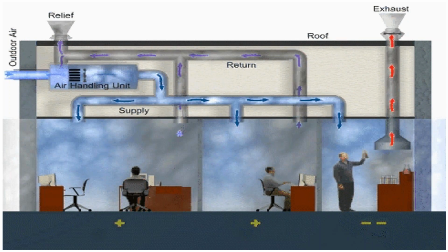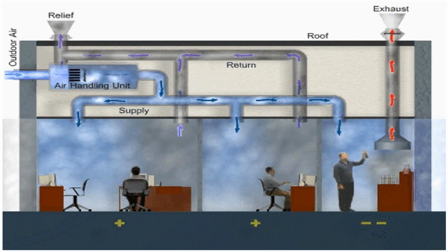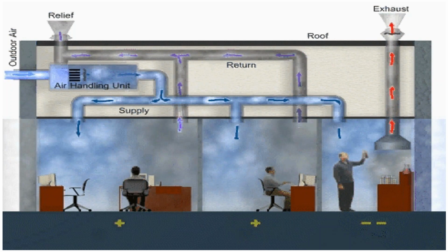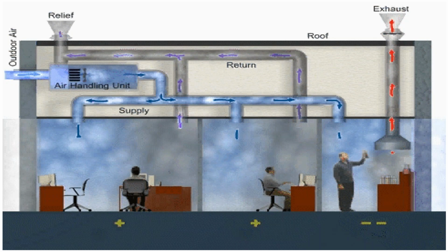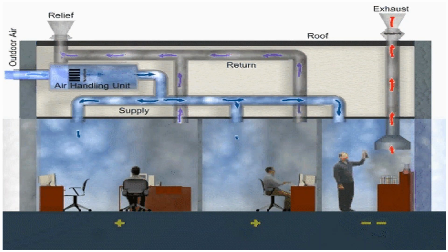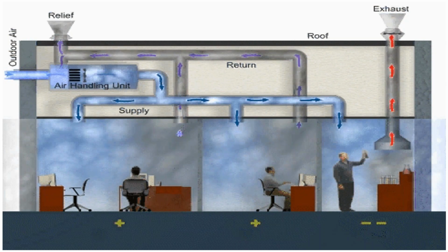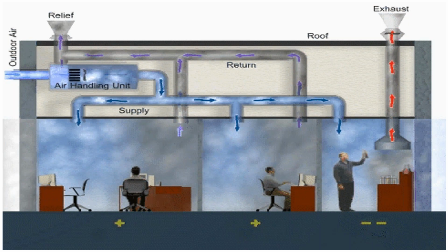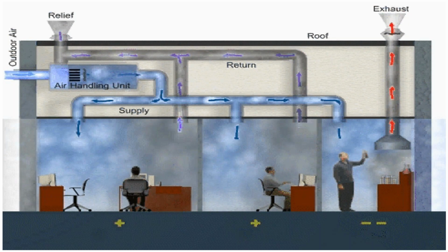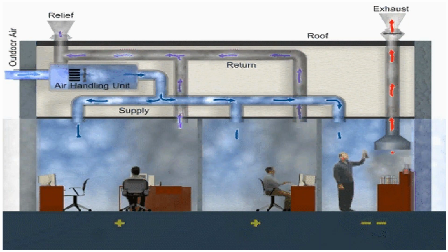Because we know outdoor air is no longer fresh. It is contaminated, so it does need to be cleaned when it gets into the actual space where we have individuals working or perhaps producing research materials or pharmaceuticals, for example, or some kind of products. So we take it through the air handling unit. Air handling units are fantastic at heating, cooling, humidifying, and dehumidifying. They suck at air filtration.